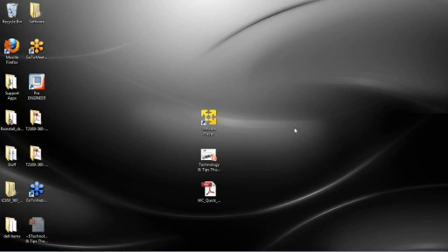that supports that WT part. So if I had spec documents or Word documents or any other type of Excel file that supports that Pro-E file, what I have is a bucket to which I can relate a number of different objects and keep version and revision control. So when I go to look for a specific part file, in this case a CAD part file, I might do a search for part 1, 2, 3, 4. You will see the CAD document 1, 2, 3, 4, but you also will find the WT part 1, 2, 3, 4, and you can see any other supporting documentation. So when you go to find something, you are finding everything that is directly related to that object.